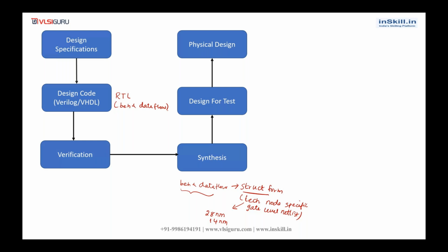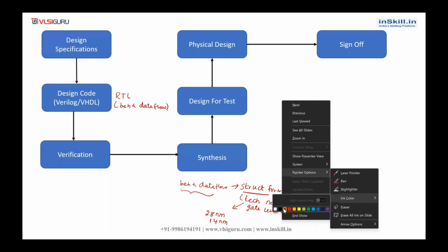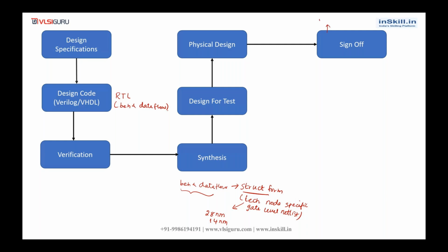Next is the sign off. During sign off, we will be doing physical verification, another one is STA, and the third one is LEC, logical equivalence check. Physical verification is actually to verify the layout of the circuits. That is what physical verification is.